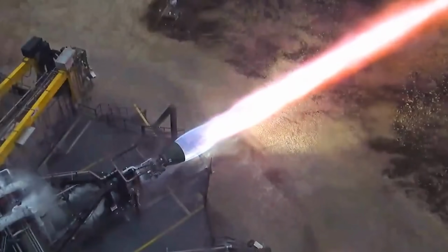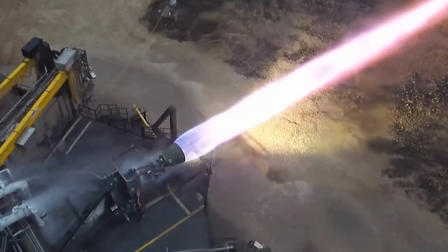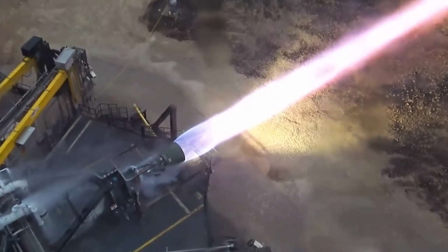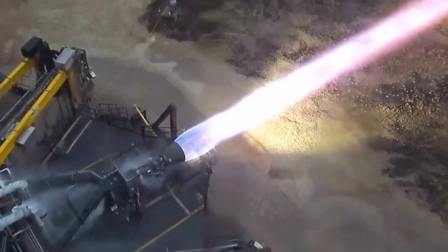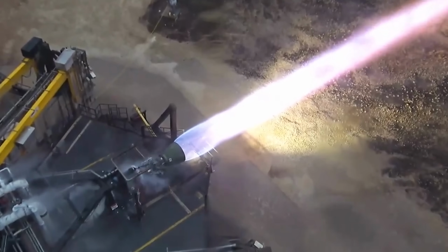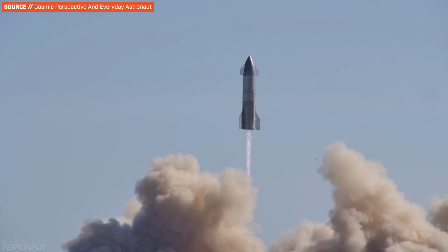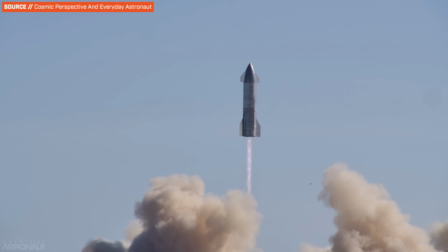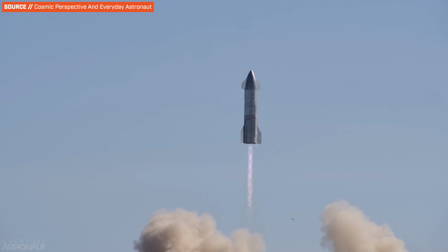Now, of course, this all varies drastically by propellant type, engine output, and all sorts of other variables. But in general, our example helps illustrate full flow's biggest advantage. What this means is engineers can either reach their power levels at much lower temperatures in their turbines, or they could potentially increase the power of their engines, assuming they've designed a system that can handle high heat loads, or, of course, some happy compromise of both.